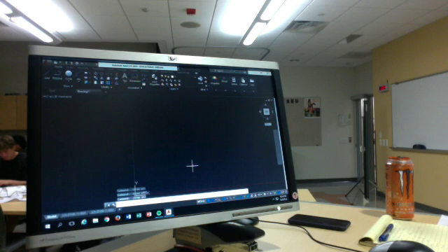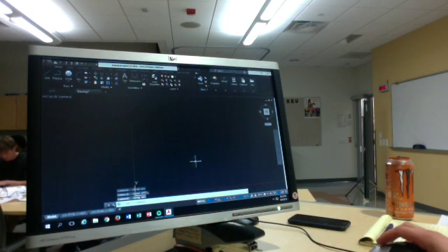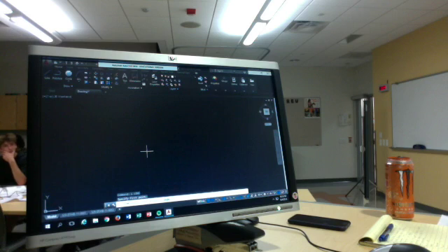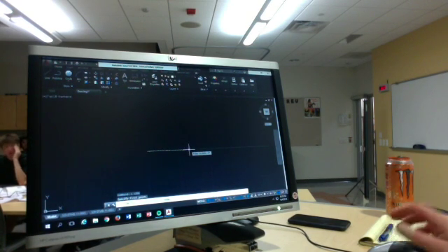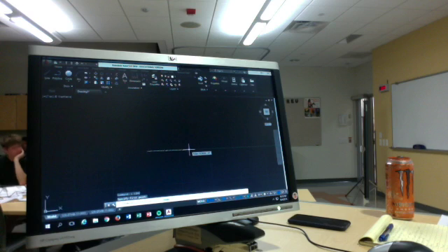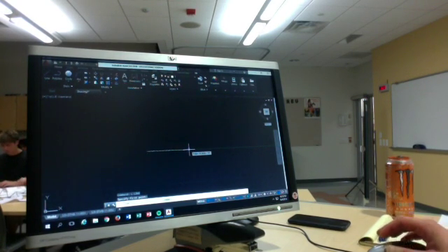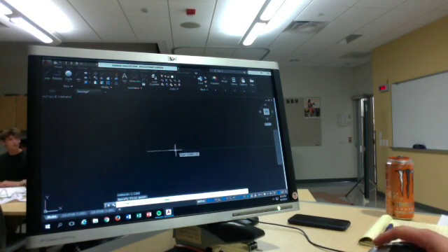Okay. All right. So we're going to select the line command. You can grab it from the tool panel up top, or you can type in L, type in line. We want to have it right on the grid. So what it says to do, yes, specify the grid line, move the cursor horizontally to the right 10 grid spaces. Okay. So yeah, we're going to go 10 grid spaces.